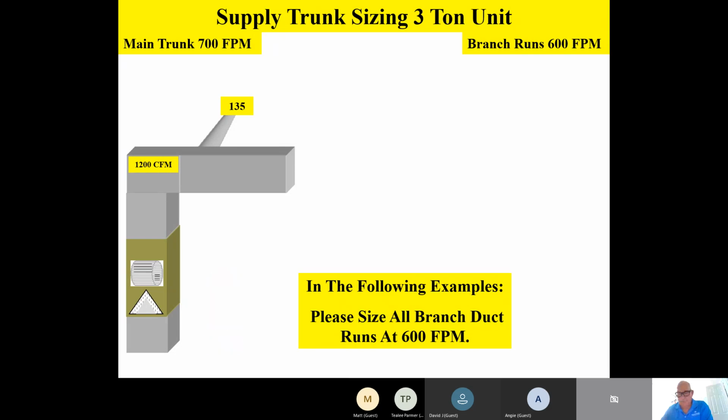Okay, well, as we continue doing takeoffs, let's go ahead and do another one. We have another takeoff at 150 CFM at 600 feet a minute velocity. So referring to your air duct calculator at 600 feet a minute velocity, line up 150 CFM air volume for your velocity design point, and then go over and see that that gives us a little over a 6.5-inch round duct.